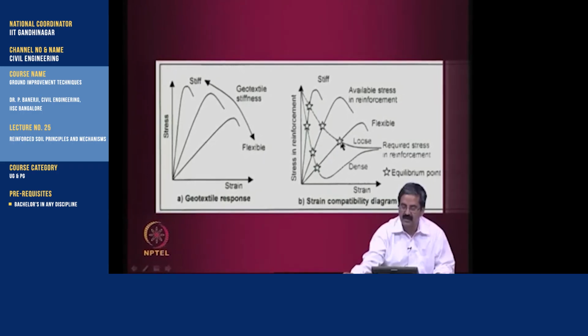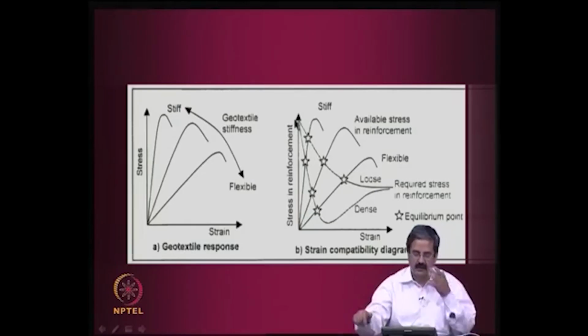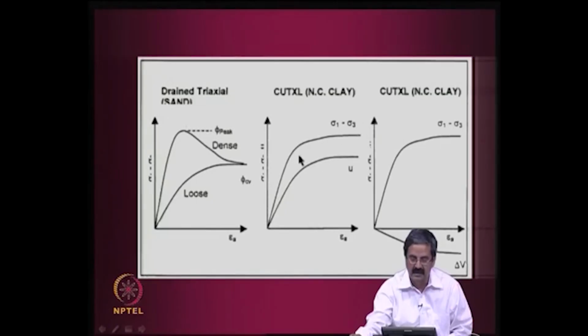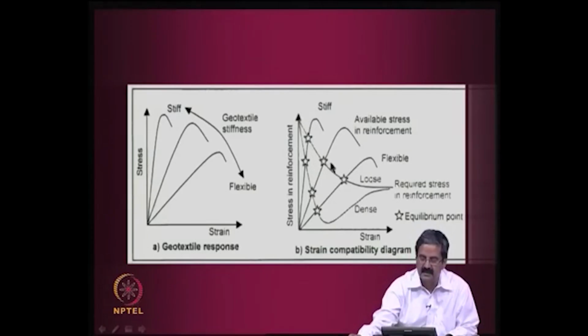But then what is this? You have seen in the previous figure, in the case of loose materials, dilation. If you just compress a loose sand, it continues to compress, like from 0.1 to maybe 10%, it continues to compress. Whereas, in the case of a dense material, it is like this, there is an initial compression, then it starts increasing, right.